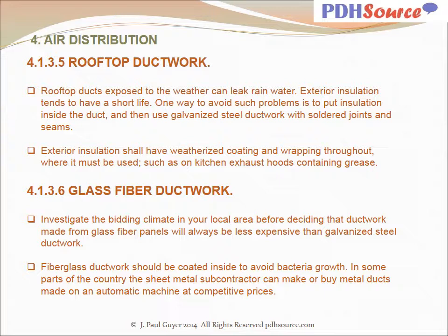Investigate the building climate in your local area before deciding that ductwork made from glass fiber panels will always be less expensive than galvanized steel ductwork. Fiberglass ductwork should be coated inside to avoid bacteria growth. In some parts of the country, the sheet metal subcontractor may make or buy metal ducts made on an automatic machine at competitive prices.